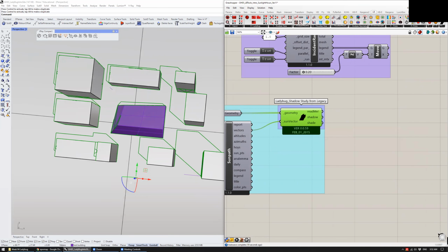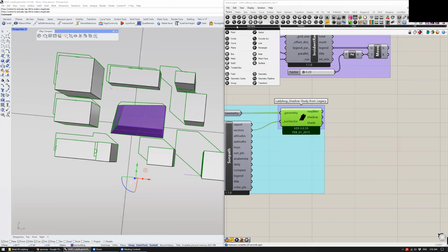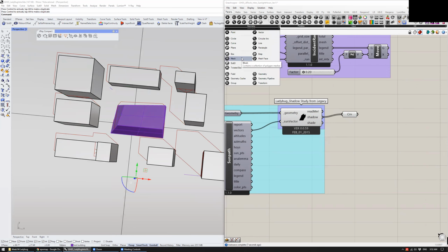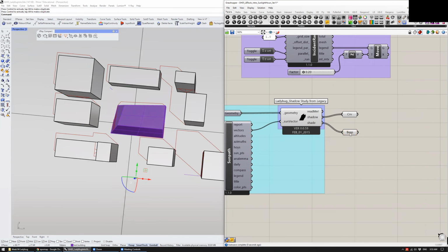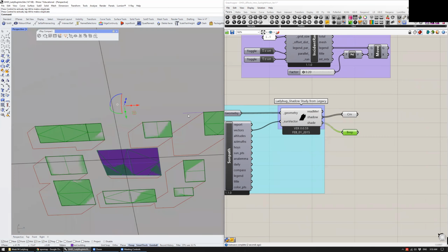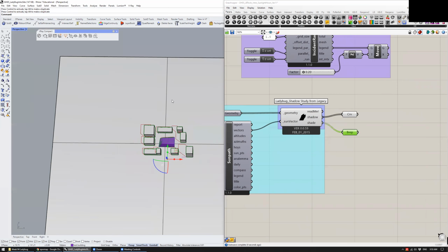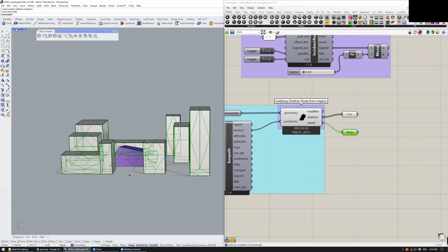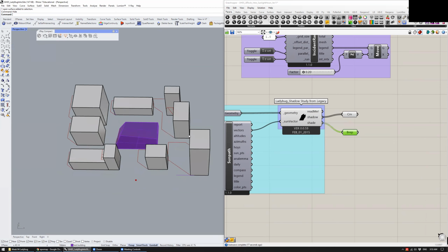These are outline curves. So if you want to isolate them, go to your geometry tab, pull in a curve component here, and you'll get that. Out of here, the shade, you can put in a brep component like that. I think it's hidden because of my overlapping ground plane geometry, so I can hide it for a second. But there is a brep, or actually because I'm in shaded, no, I am shaded. Okay.